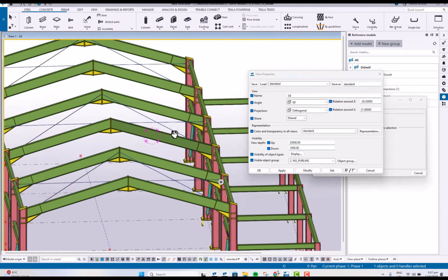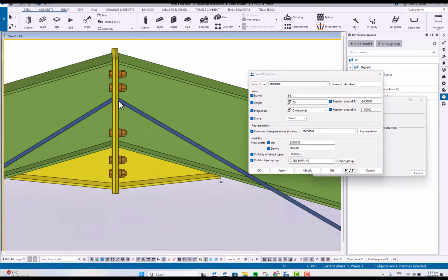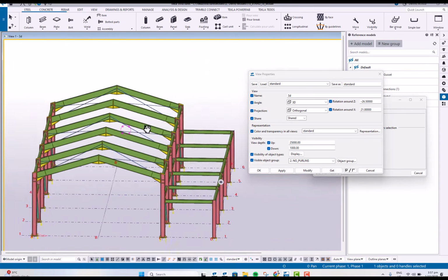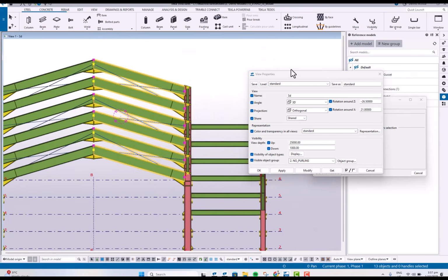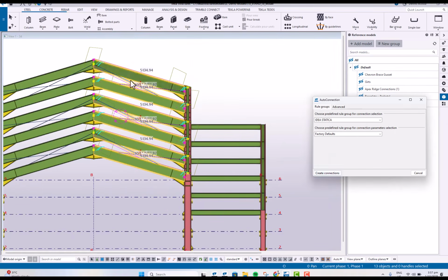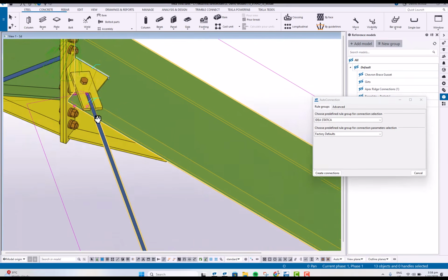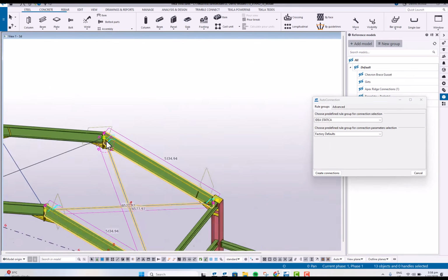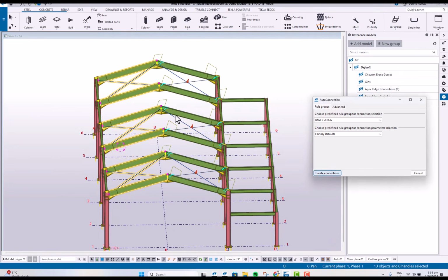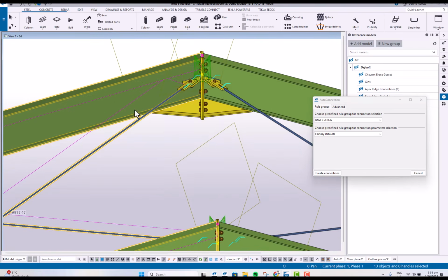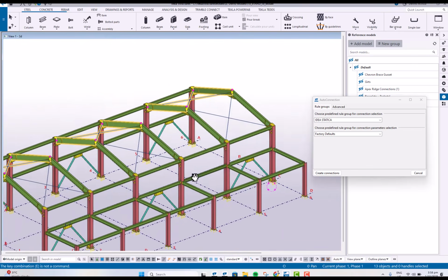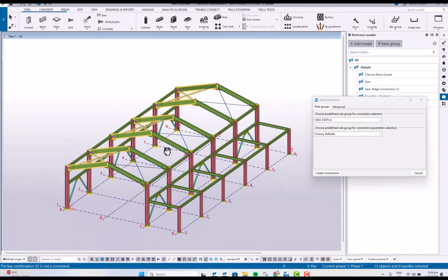So this roof brace, remember earlier, Engineer Jean moved that one to the center. So all I have to do is select again the roof brace and the rafter, and then hit create connection, and you will have this connection similar to what Engineer Jean created in IDEA StatiCa. So same thing, there you go. All right, and done. I have already finished my connection here.